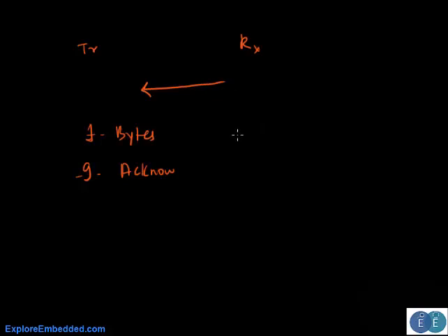say this is our clock, and this is the 9th clock, and 8 bits have already been transferred. So this is the clock line, and what it does is it holds the data line low.